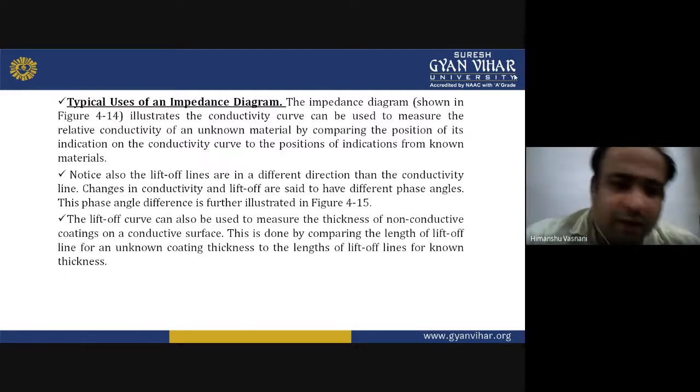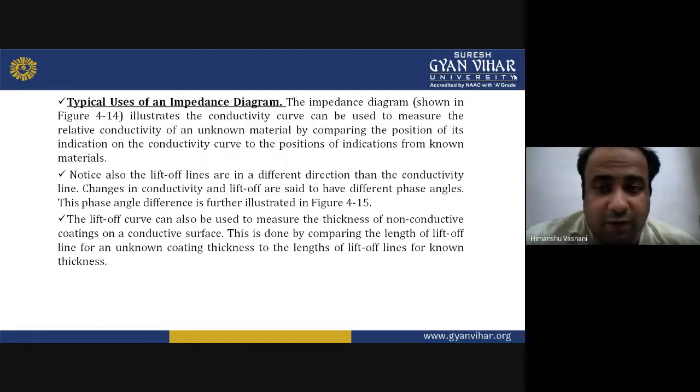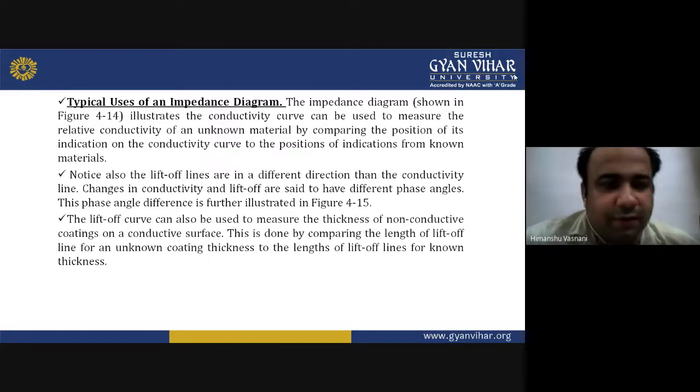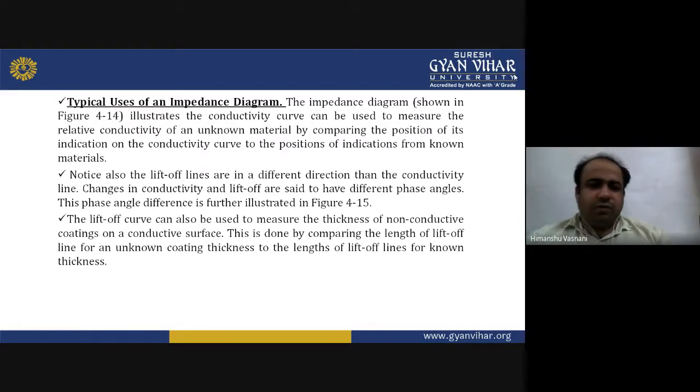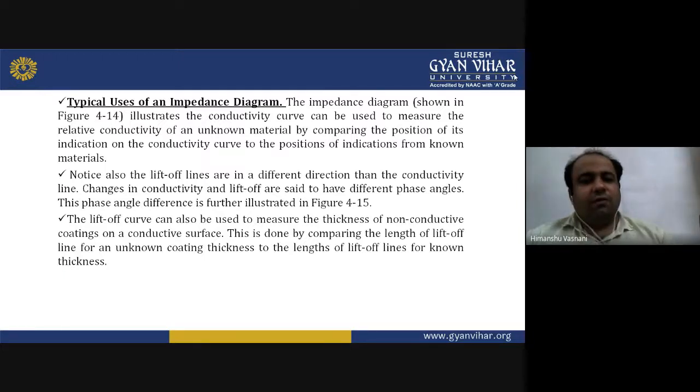You also know that the lift-off lines are in different directions than the conductivity line. Changes in conductivity and lift-off are said to have different phase angles, which I will also show you in the figure. The lift-off curve can also be used to measure the thickness of a non-conductive coating on a conductive surface. This is done by comparing the length of the lift-off line for an unknown coating thickness to the length of the lift-off lines for known thicknesses.